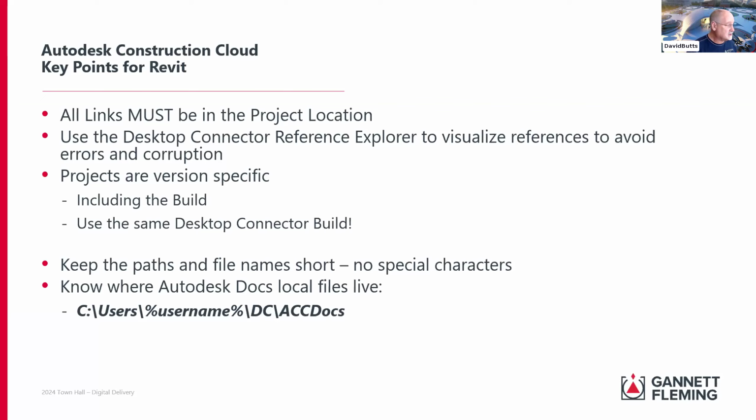So it's like the old days of putting things on your local hard drive and then linking or XREFing an AutoCAD drawing into another one from a local hard drive to a server. Not everybody in the company has access to your local hard drive. So you don't want to create those kinds of links. And back in those days, you'd want to have all those files in the same location, or at least on the same server. It's the same rule in here. It still applies. So make sure that any images, any PDFs, any DWGs that you're using are in your ACC environment. Don't link them anywhere else. That's rule number one. Make sure you get that squared away.